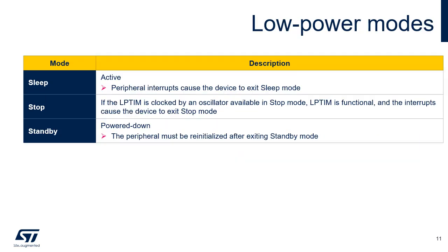The low-power timer peripheral is active in sleep and stop power modes. It's powered down and therefore not functional in standby mode. The low-power timer wakes up the microcontroller from either sleep or stop modes. All DMA requests must be disabled before entering sleep, stop, and standby mode.